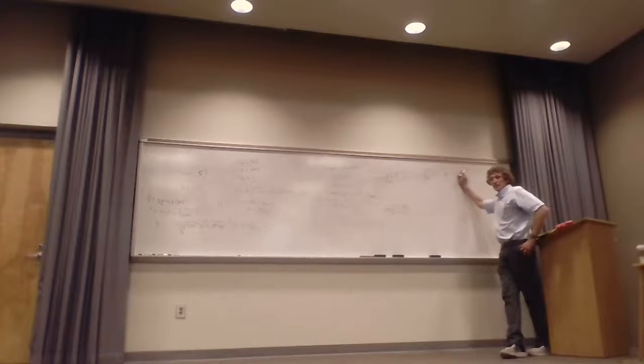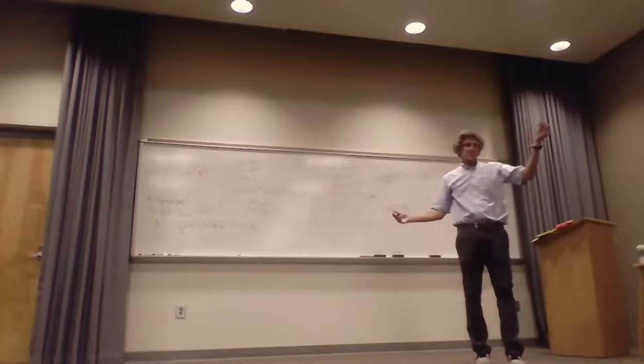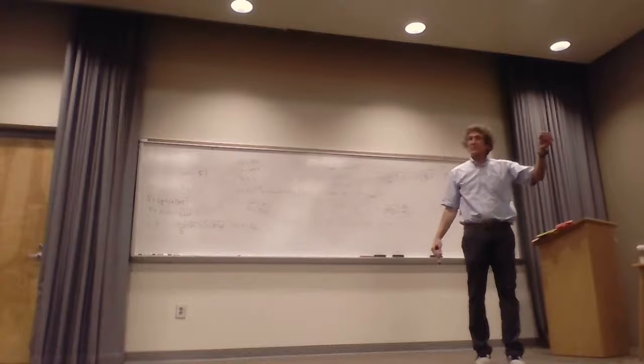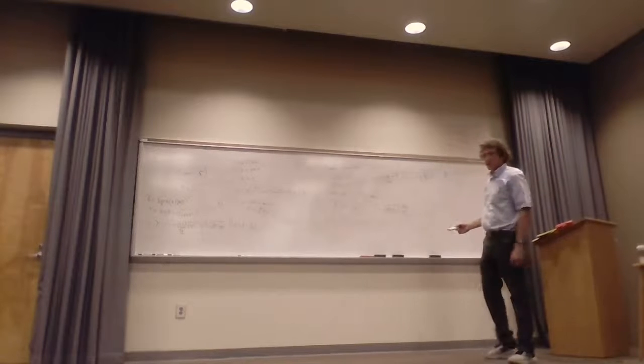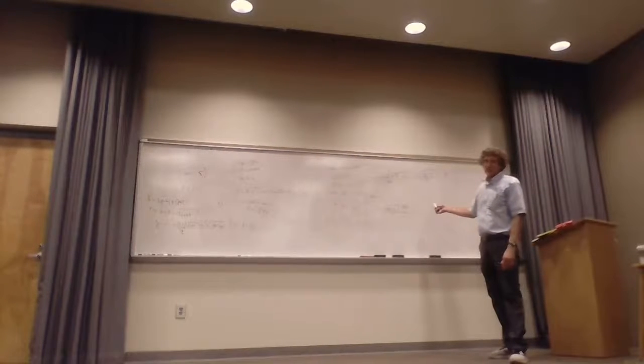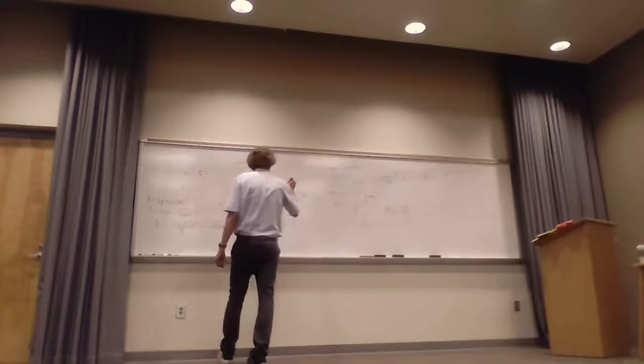Y'all with me on that? That was less than 1. So that would be, now that's in ohms. What is the characteristic impedance of this region at, say, 10 to the 9th hertz in air? It's that of free space. What is it? 120 pi or 377 ohms, right? So this is much, much less than that of free space. Do y'all understand that, eta naught of free space? Maybe I'm assuming too much.